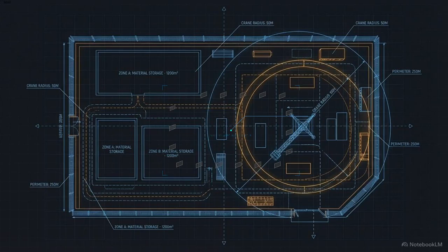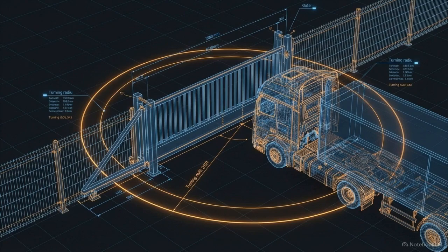Step 1 is establishing the absolute perimeter. Starting with your blank site footprint, draw the temporary fencing to lock down the boundary. Next, establish your primary vehicular gate on the street edge, offering the easiest turn-in radius for heavy deliveries.